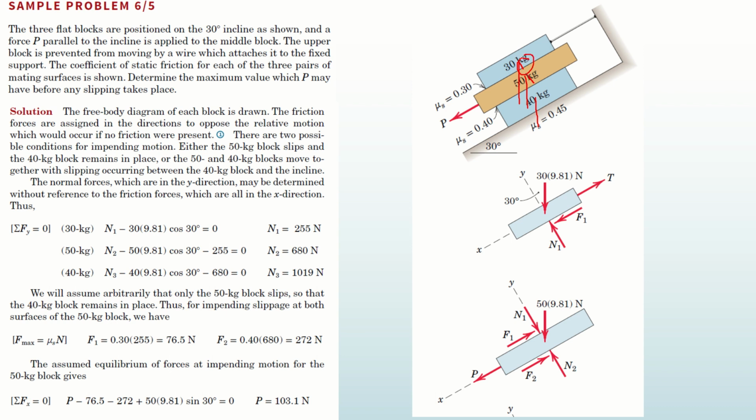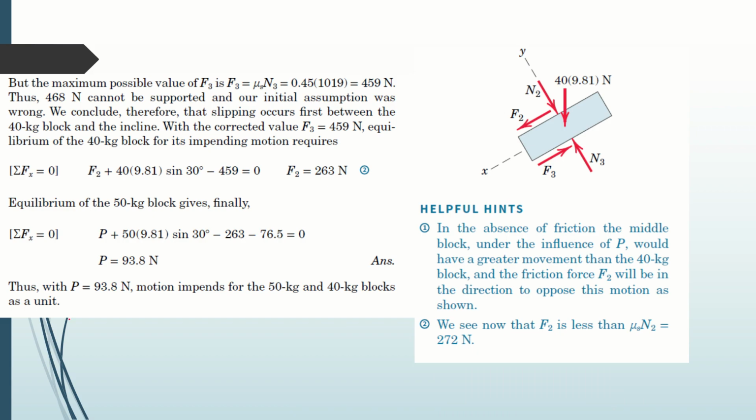So you are going to first balance this point, then balance this point, and the reaction forces of this point are going to be transmitted to these points also. So you have to add these together. As you can see in this case, they have been introduced here and here. Then you say F1 is equal to F2, F equals mu N, and then sum of all forces. The universal truth for equilibrium is that the sum of all forces along x equals 0 and the sum of all forces along y equals 0, and hence you can easily solve for the value of P, which is right here. That is 93 newtons. Wow. Only this much force. How easy was that? This is again a part of your book. You can solve it. If you have any problems, do discuss with me. Thank you. This would be all for today.